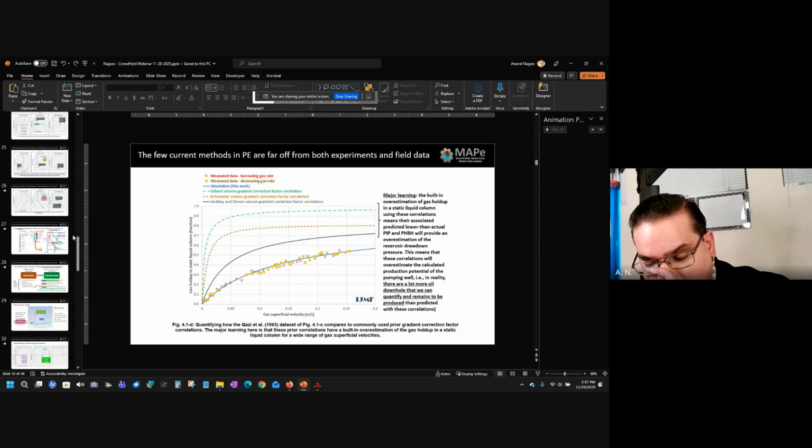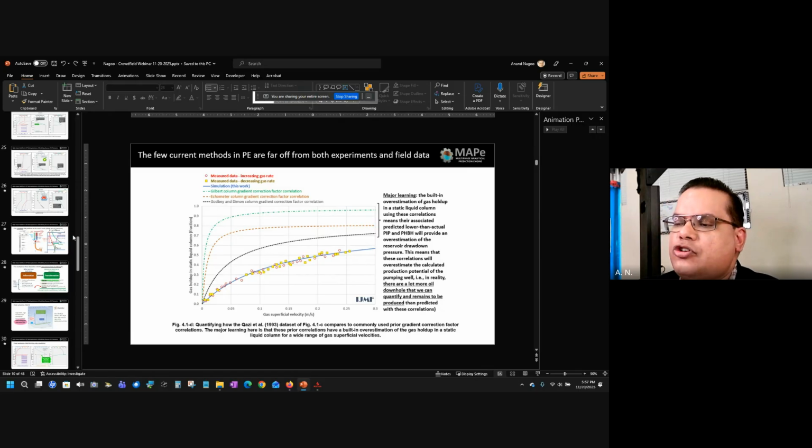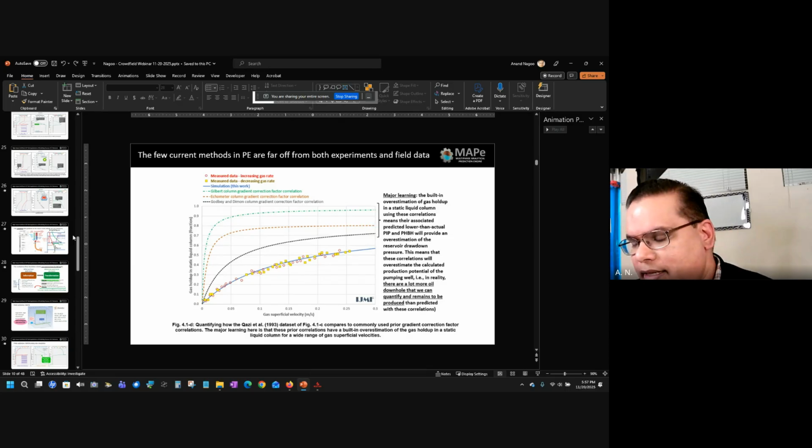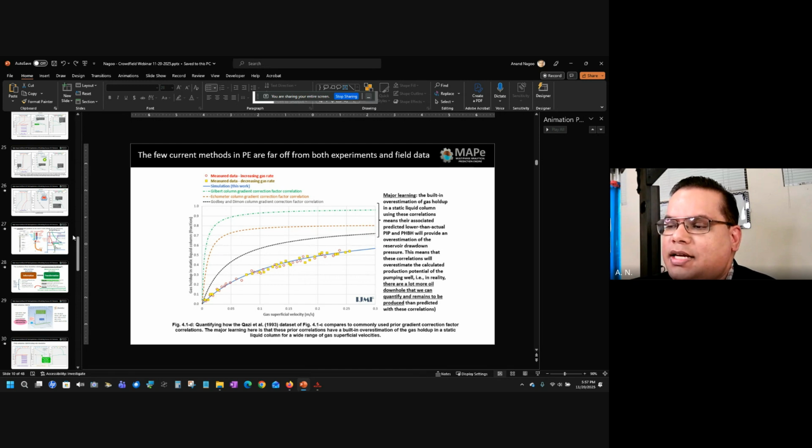No, no, you're totally right. Because the wonderful thing about recirculations and the flow patterns is that each one of these flow patterns, including their local behaviors, has a macroscopic repeatable behavior. And that takes a long while to actually understand. But if we're not even accounting for them, so for example, if we don't even know that there is slug flow or churn flow in these liquid columns, then you don't even think about recirculations as a concept.